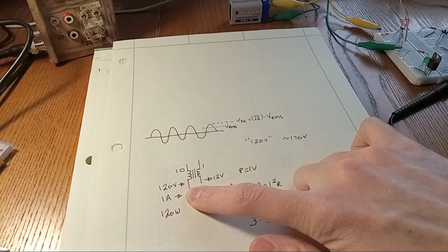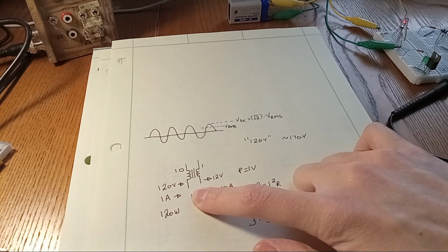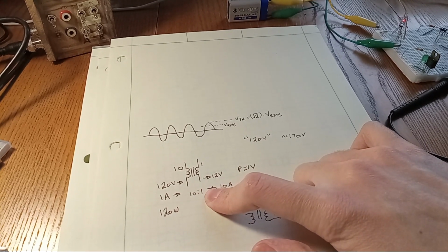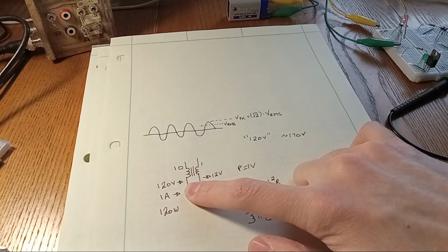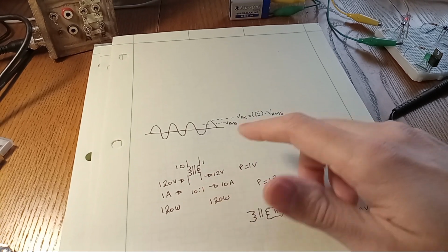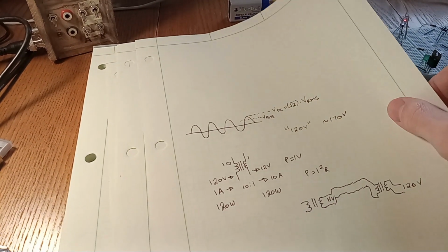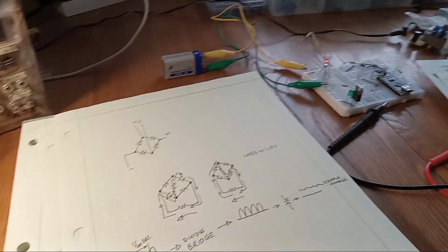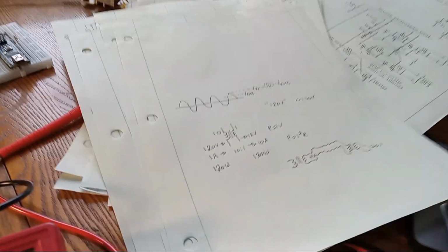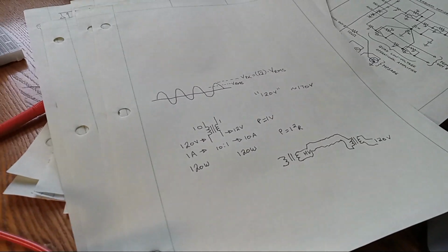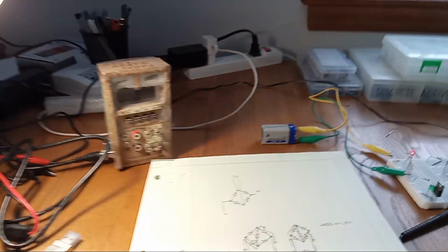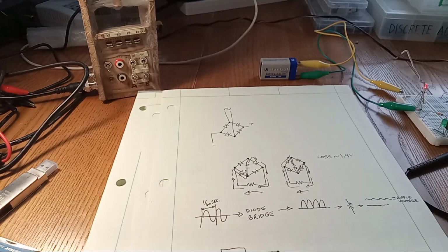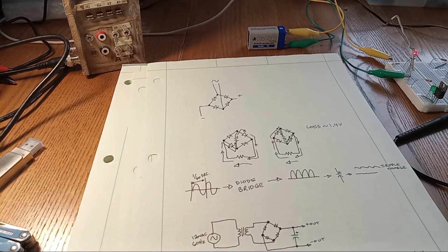We talked about how transformers are capable of converting one voltage to another voltage depending on the ratio of turns between the 2 coils. Note that you can make a transformer with 1-to-1 ratio, which simply passes the voltage through unchanged. This is called an isolation transformer. It is useful if you are working on line-powered equipment and you do not want to get a potentially lethal electric shock.